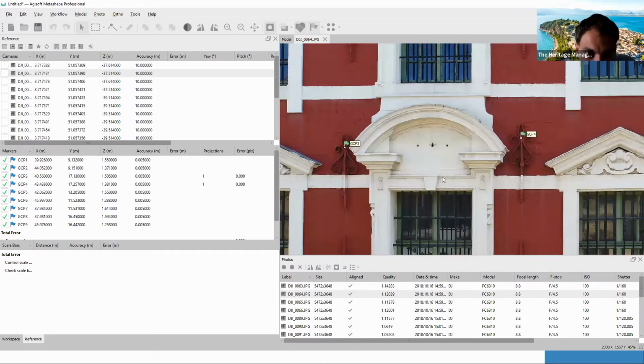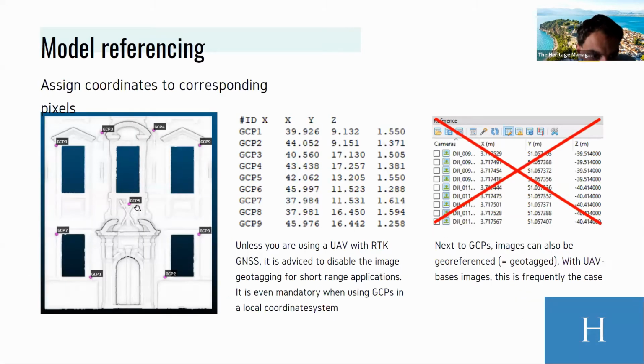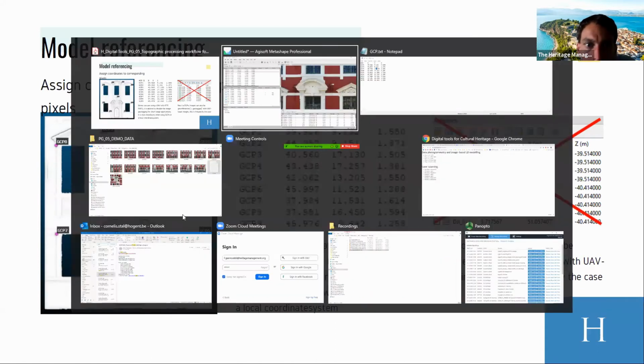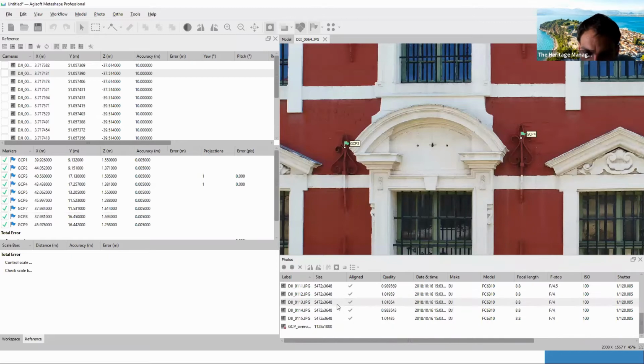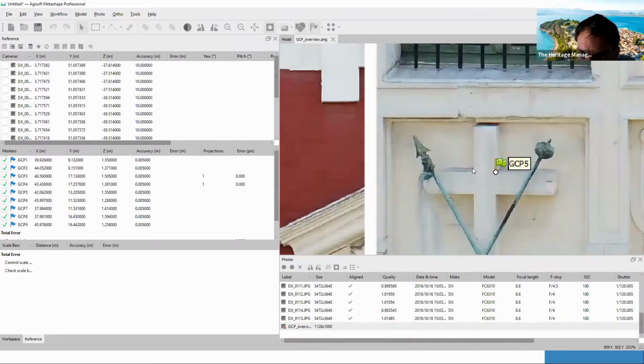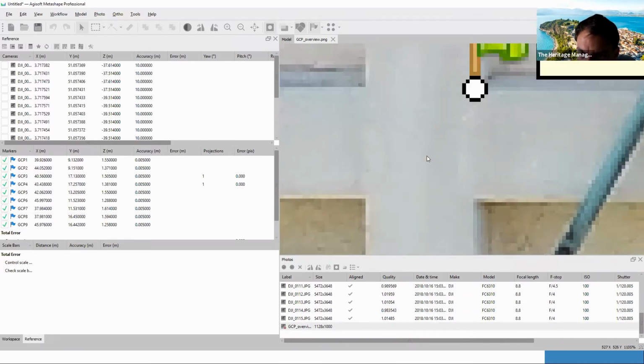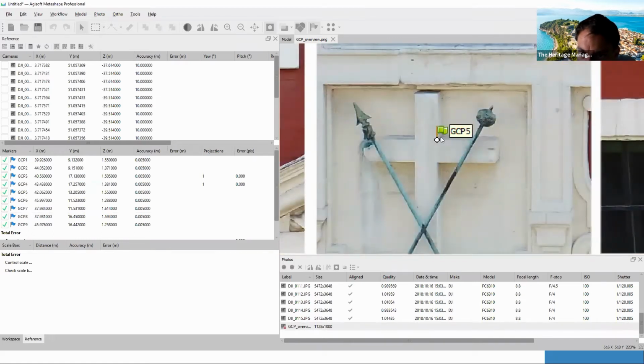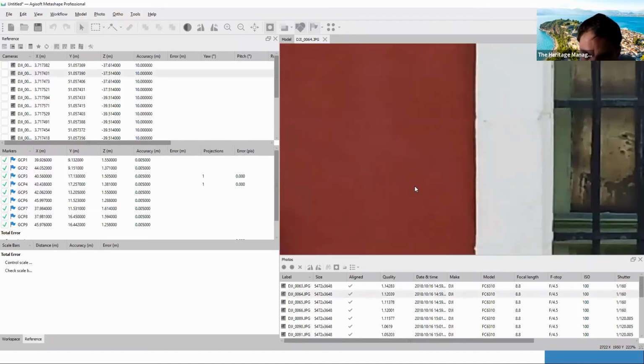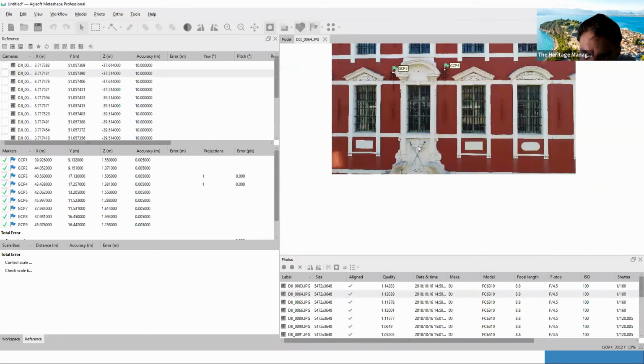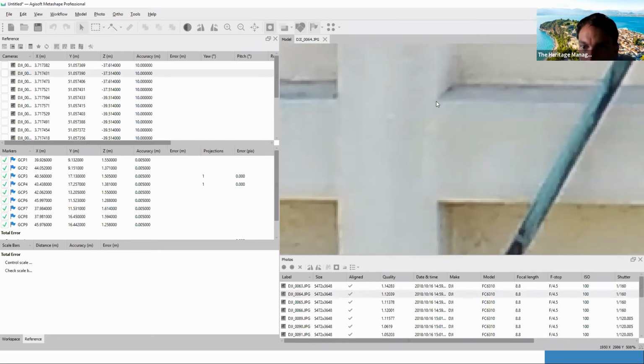have any redundancy yet. The next thing I will select is this other easily distinguishable point, point number 5. So let's see where that is situated. Point number 5 is on the right, the inner edge of the cross. Also visible here on this photo. So the right upper part of this cross. Right click, place marker, GCP5.